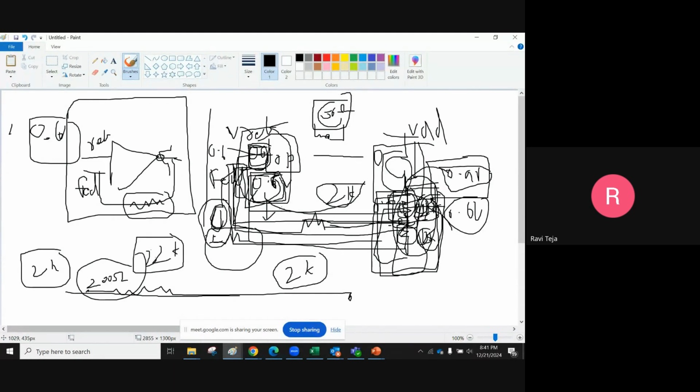You might think in that way, but what the schematic designer will do is add some parasitic margin. Every schematic designer will design his circuit with some margins. If it is anywhere from 1.95k to 2.05k, the feedback will still be 0.6 volts, because we design the circuits in such a way.